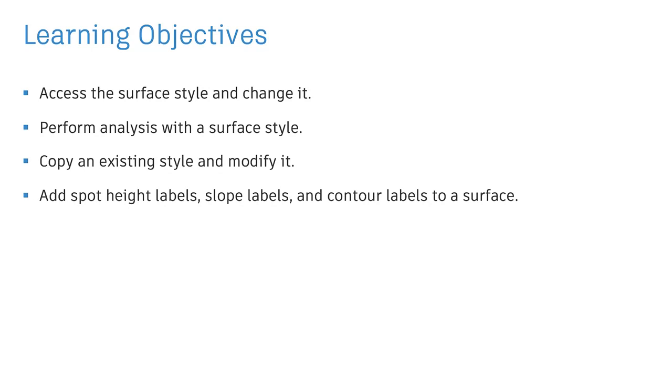Now you'll learn different ways to assign a new style to a surface. We will perform surface analysis using a surface style. You'll learn how to copy an existing style and modify it to create a new one, and we'll show you how to add spot height, slope and contour labels to a surface.